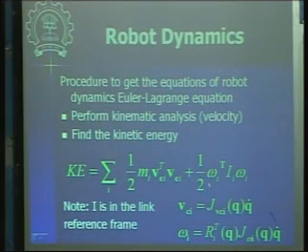So we want to avoid that. So here the inertia of this link is expressed in a reference frame which is attached to the link. Hence you have to introduce this rotation matrix over here to take care of the transformation of omegas to the link reference frame.